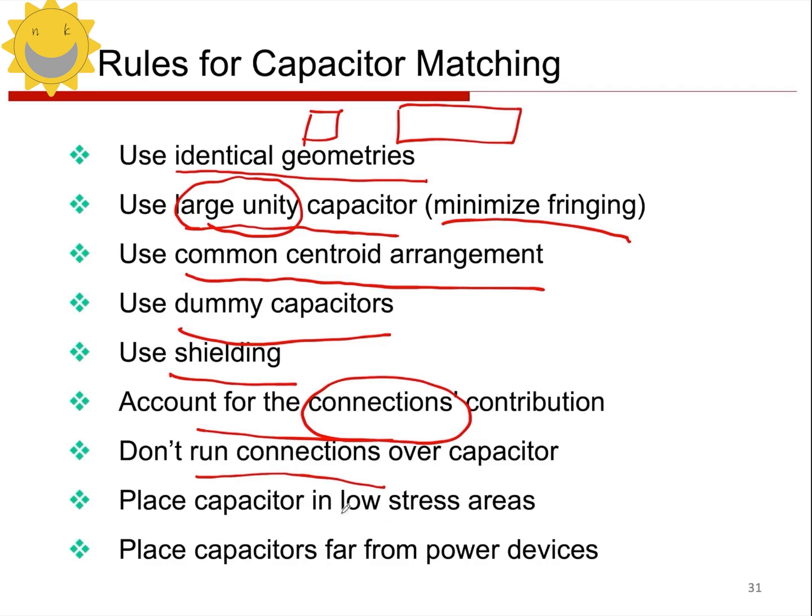Well, finally, the capacitor should be placed in a low stress area and away from power devices so that the fatigue of the capacitor will be better. So the above are the matching principles that we should pay attention to when drawing capacitor devices.